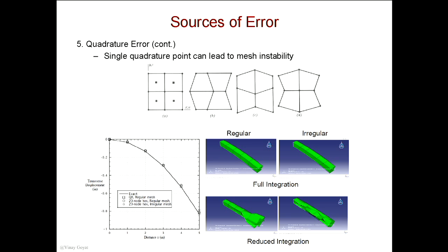By the way, C3D8R is, I believe, the default. If I run an analysis and apply a load, I'm going to get results that don't make any sense. And some people don't look for these kinds of things. They just run the models and just get the stress. They keep moving. Your job is to be a police for finite elements, right? You should know better.